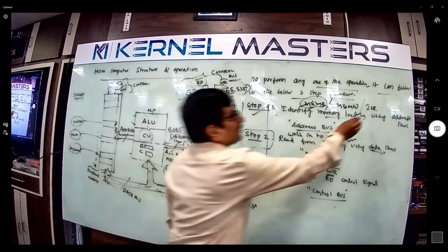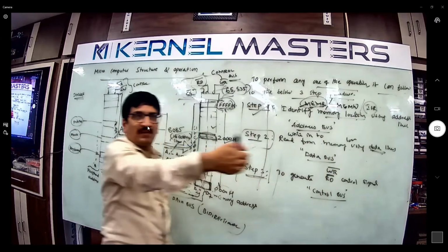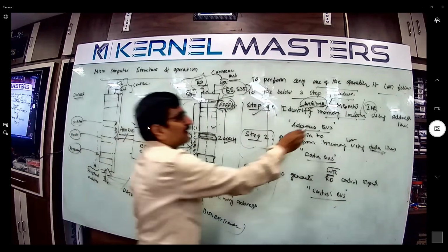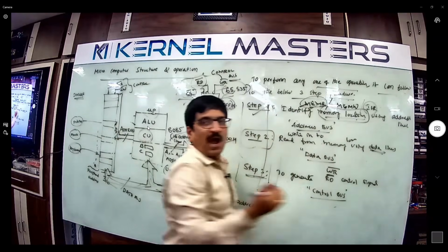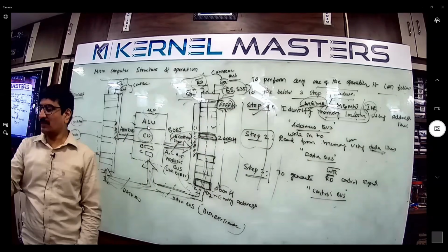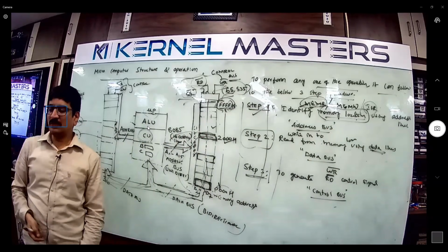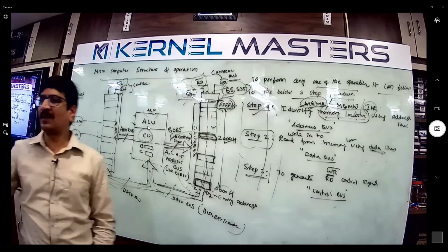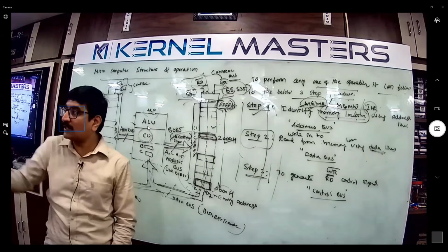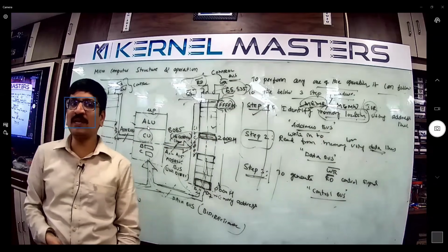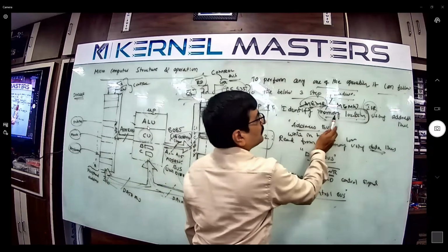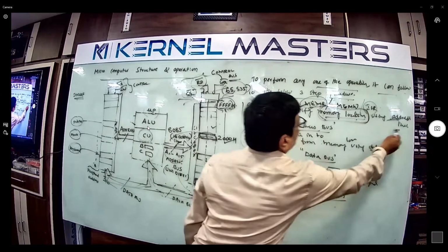Tell me the IO read operation. IO read is nothing but reading data from the keyboard, an input device. What is the first step? Identify the IO location, not memory, the peripheral location, the keyboard address. The keyboard address is 60; almost every laptop keyboard address is 60. It is mentioned in the manual. People who communicate with hardware should know the address of the device, which is mentioned clearly in the manual. We identify the peripheral address using the address line.